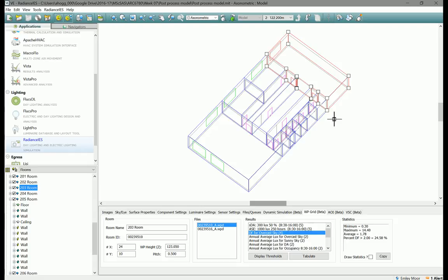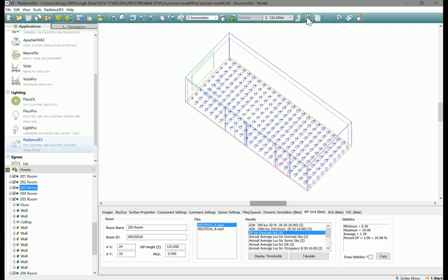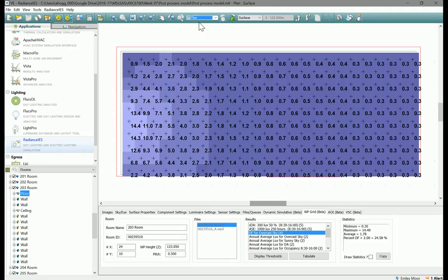Nothing seems to have happened. Okay, nothing's obviously changed on screen. What you need to do in IES, you need to click on this move down button, move down a level. That takes you to the level of the room, and it shows us some results. Generally, change it into the plan view, and that will be a lot clearer. That will make a lot more sense, hopefully.